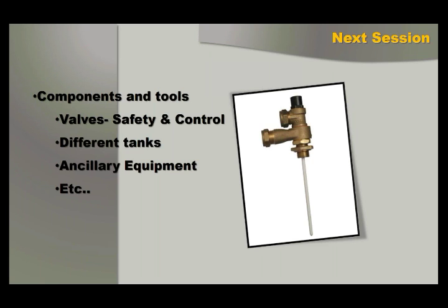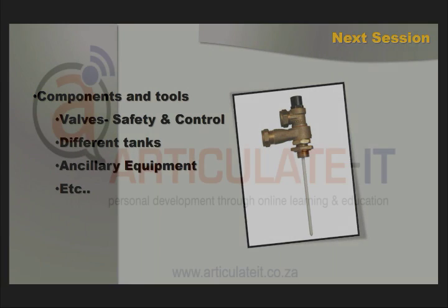There are other means of controlling overheating as well, some that are not really common in this country. One is a heat dissipator. It looks like a circular fin, sort of a radiator, installed at the top of the collector. It simply acts as a radiator, with a thermosiphonic flow through it, and that naturally gets rid of excess heat. They're not available here. I certainly haven't seen them. Again, perhaps it's something we should really look at. Somebody should look at importing.